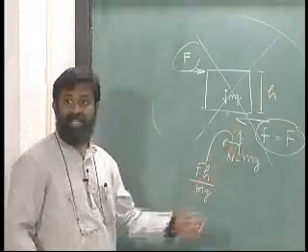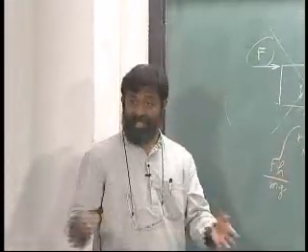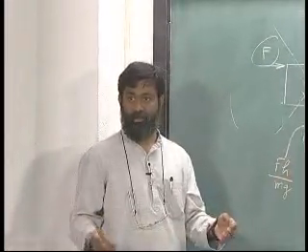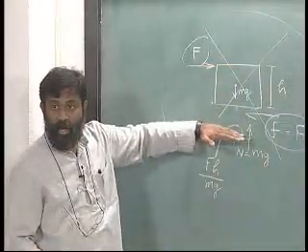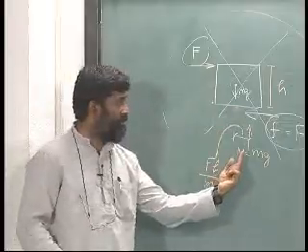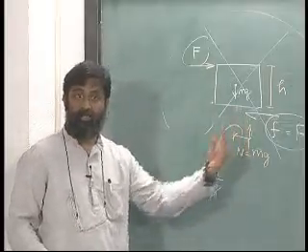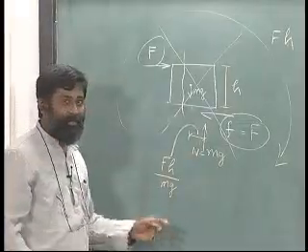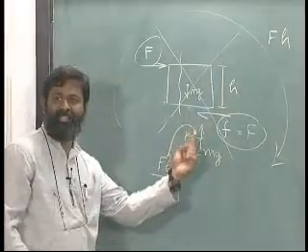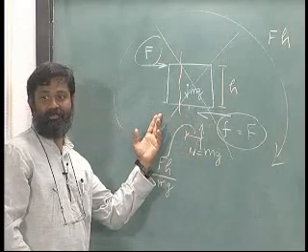What is this N? This is the net resultant reaction that comes from the pressure that is offered by the surface. So, this is a resultant, please remember that. Sometimes when I cut like this, one of the mistakes people make is they will say okay, N is acting like this. There is no N here.